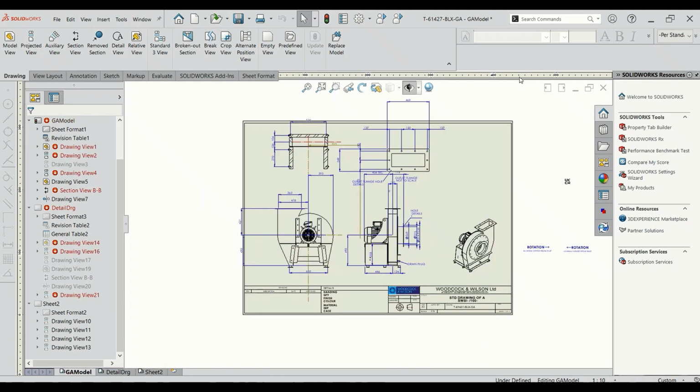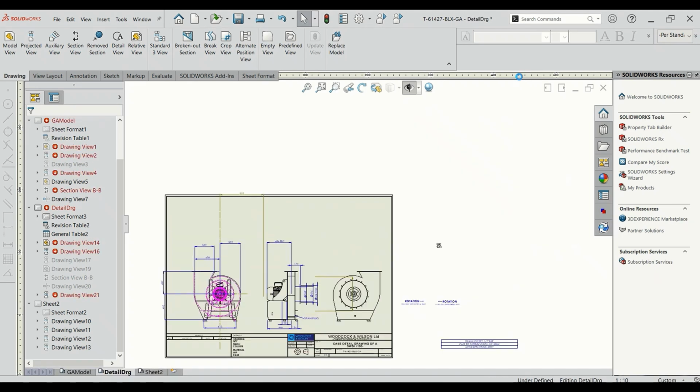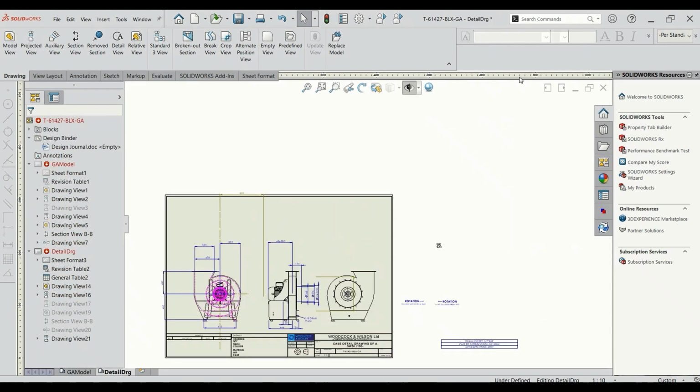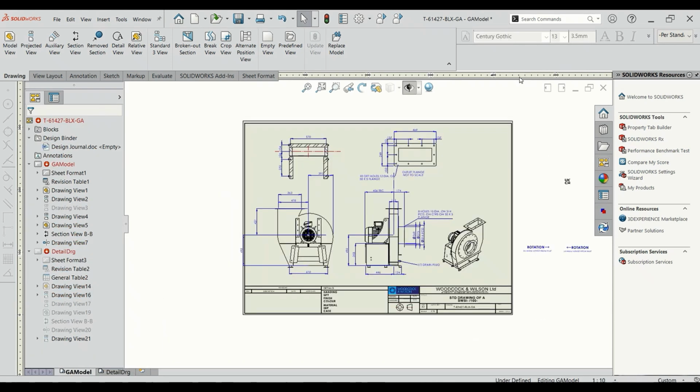Details can be added by DriveWorks or can be fed to PDM, which will in turn push the information onto the drawings. PDM can also push information from ERP onto the drawings, or from parts onto the ERP, such as product codes for purchasing. This is helpful because if a designer changes parts in an assembly, then the product code of that new part could be pushed to the ERP when the model is checked into PDM.